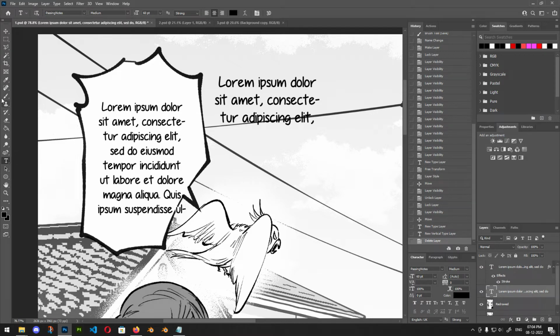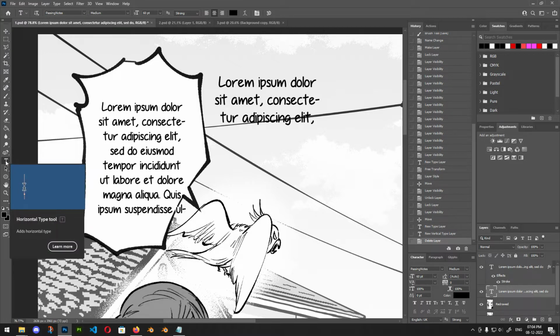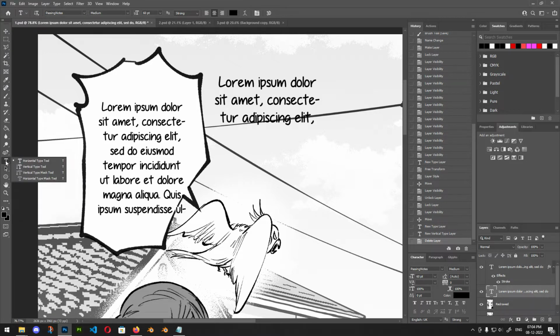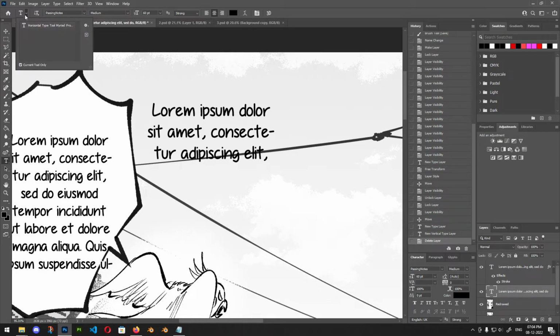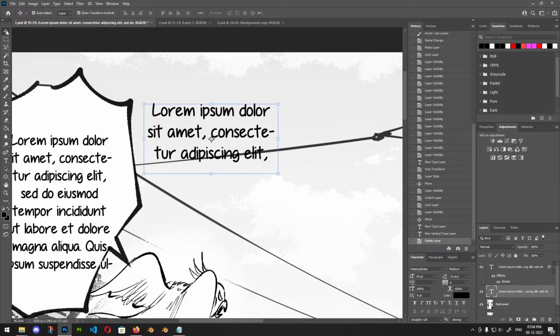And yeah, to change the options here, you have to hover over the icon and right click, then you can select whatever tool you want. Now we are using the horizontal text tool. This also shows the horizontal text tool here in the tool menu bar, and this button is used to change orientation. So I'll use the move tool to select this text automatically.